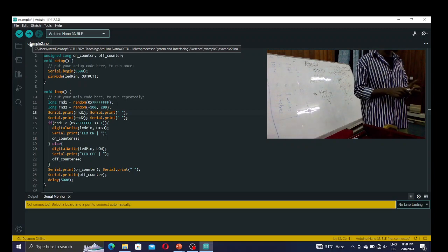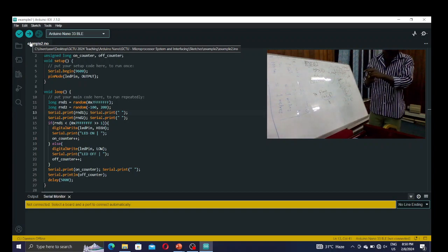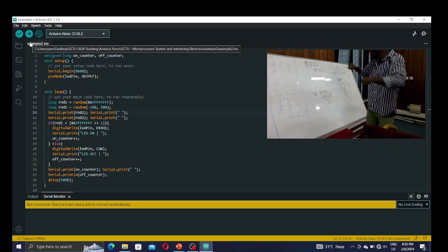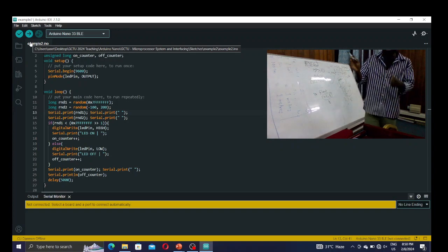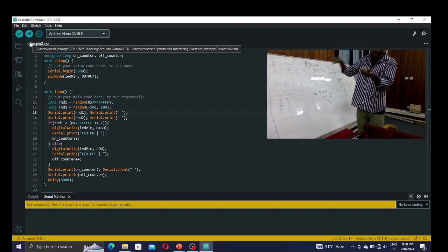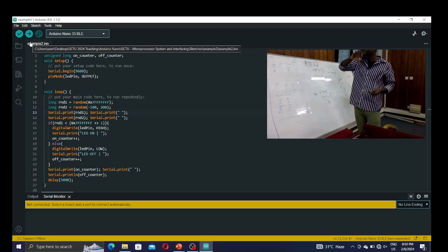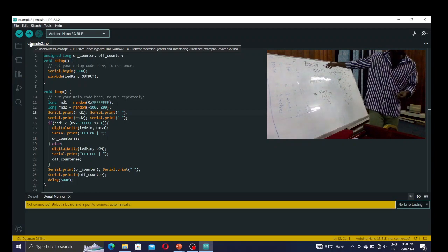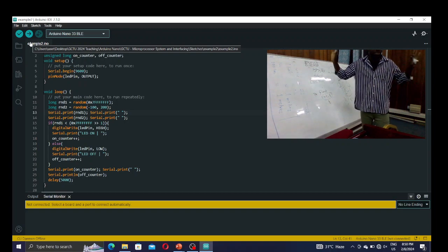So you see how easy that is? I'm just shifting. The shift just means that I remove the last bit, called the LSB, the least significant bit, push all the rest of the bits along, and put a 0 in front. So for this same number, if I say shift by 2, what does it become? Easy, right?